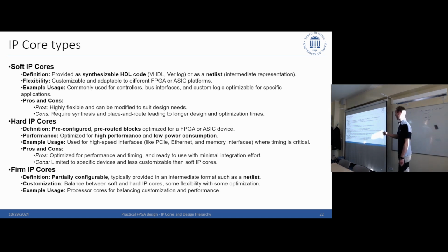But you see already a netlist is an intermediate representation, which is often hard to read. And then, of course, when you have a soft core with an intermediate representation, you will need a tool which is able to regenerate these kinds of things. Especially also often used when you get soft IP cores from HLS, high-level synthesis. Then it might be directly delivered as a netlist. So you change it on a higher level, which then goes down.